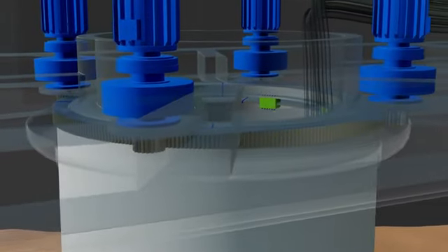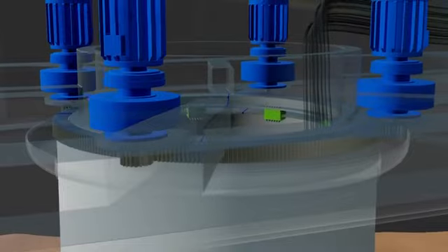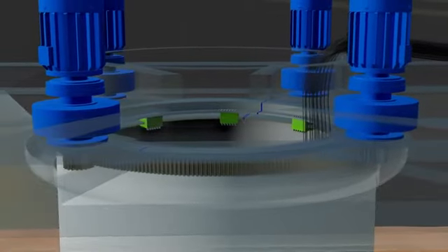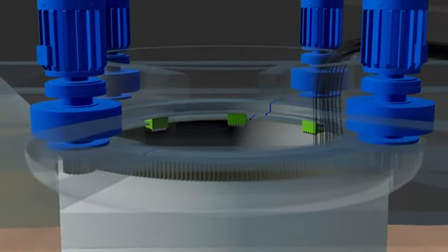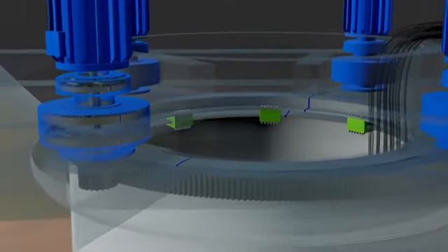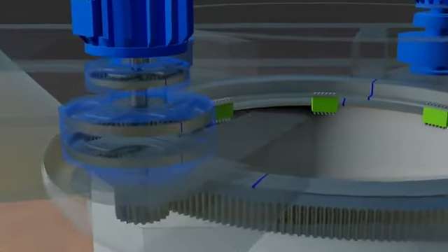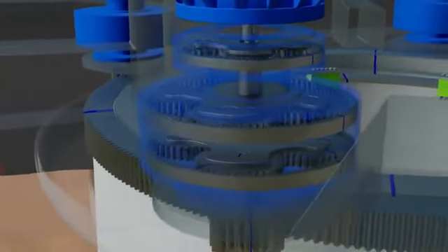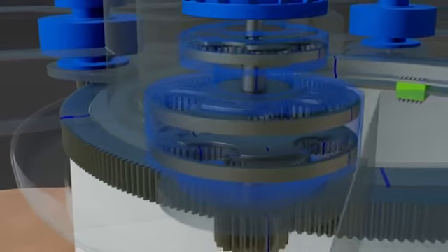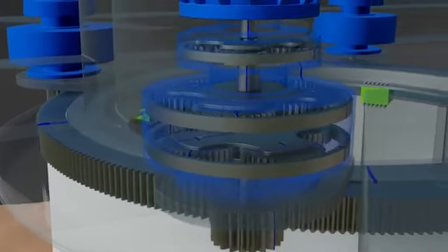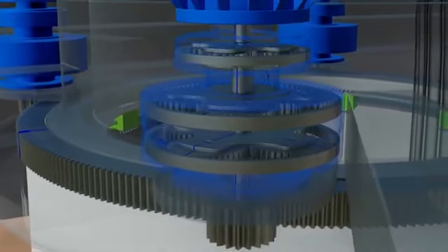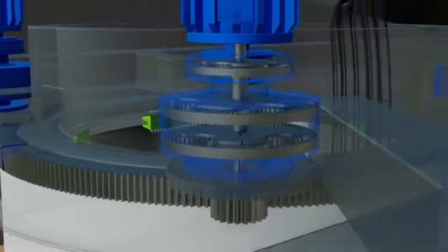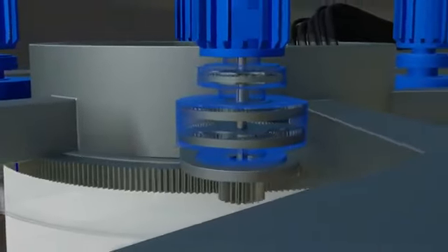These motors are similar to pitch motors but require even greater gear reduction to generate the enormous torque needed to rotate the nacelle against wind loads. In this model, each yaw motor uses a multi-stage planetary gear system. 3 planetary stages with ratios of 5, 6, and 6 create a combined ratio of 180. The final spur gear engaging the yaw ring provides an additional reduction of 15, resulting in a total speed reduction gear ratio of approximately 2700.